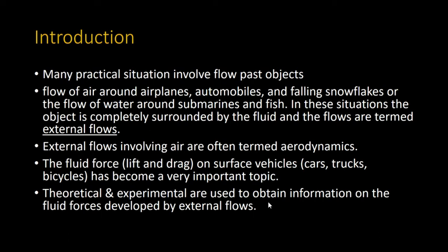For the theoretical approach, we can use numerical and analytical methods in order to find information about aerodynamic forces such as lift and drag. For the analytical, not every body or object can be defined based on an equation. That's why numerical simulation such as CFD can be used in order to obtain aerodynamic forces such as lift and drag.